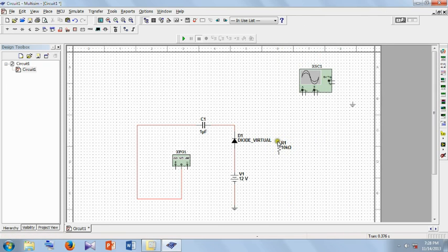Next you connect this and to this and to this point. We are calling this point as junction, you remember. And next, from the function generator negative to ground, and also from the load resistor 10 kilo ohm to ground.